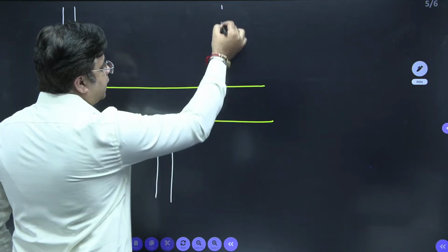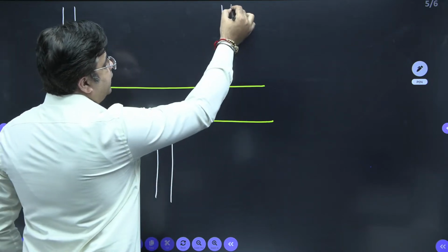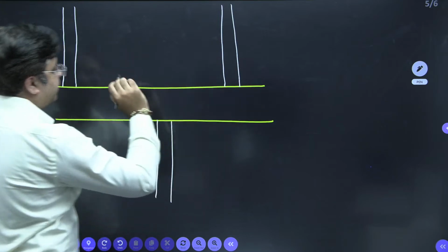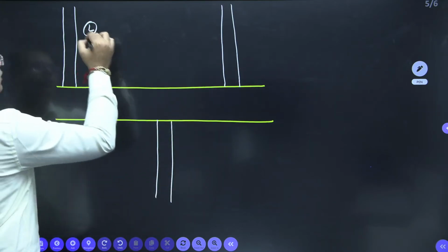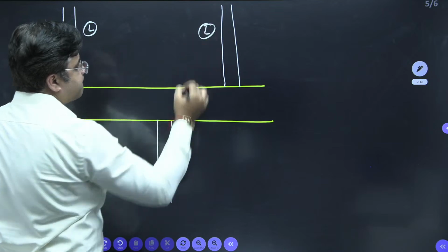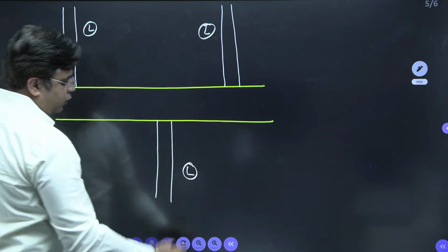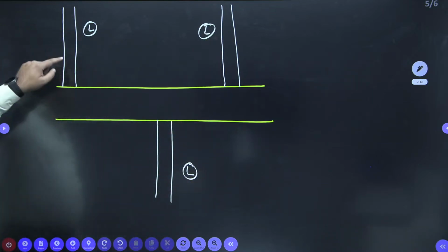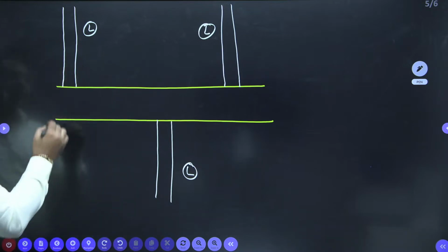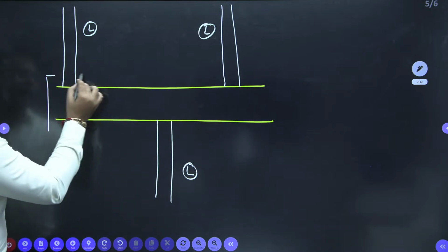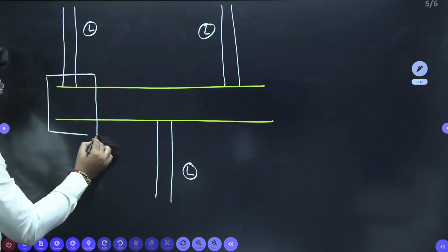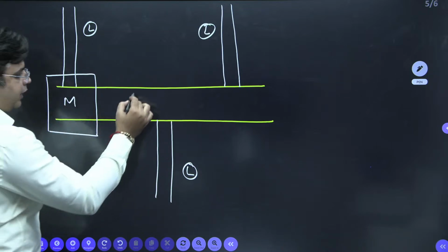This is another lateral meeting like this. So, n number of laterals meeting the branch sewer. This is your lateral sewer. So, wherever this junction is there, lateral sewer meeting the branch sewer, here you need to provide a manhole like this. This kind of manhole you need to provide.